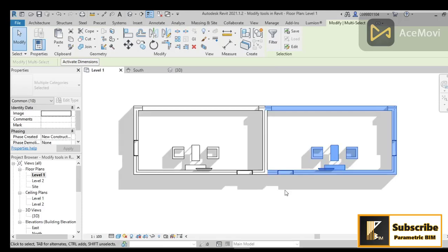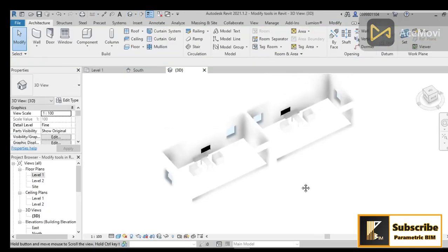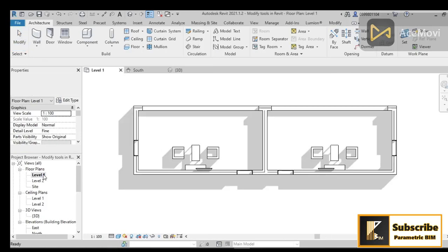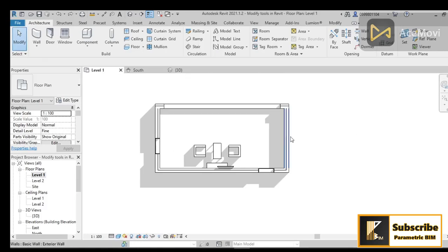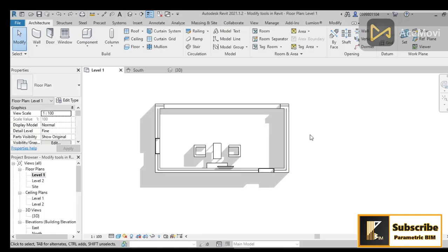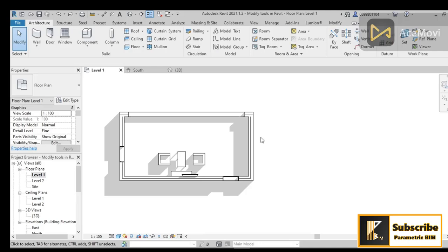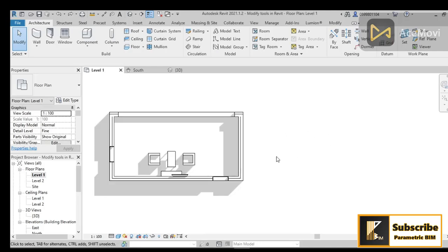Also, if you have dimensions and hatches and anything, it will be mirrored with your work, such as these. And for mirroring without having an axis, let's say that you don't have this one. Let's go back, and you don't have this one, but you have also here a lobby between these two apartments or something like that, and you want to mirror it with some distance.